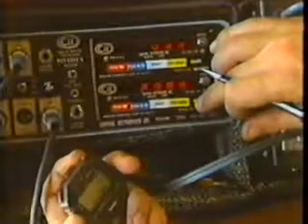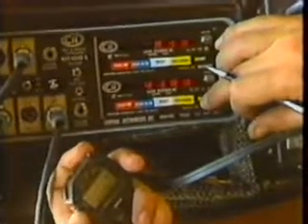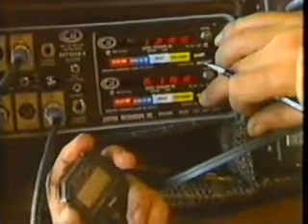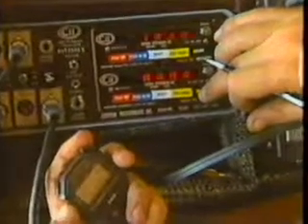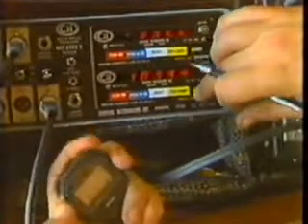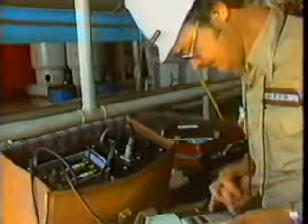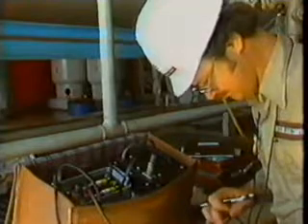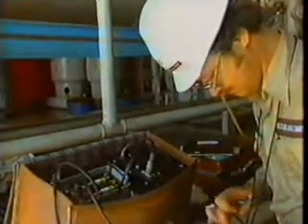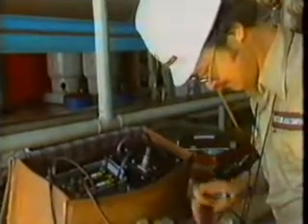Gate the two totalizers together and measure the volume with a minimum of 10,000 pulses. Stop the two totalizers simultaneously, record the readings, and zero the counters for the next measure. Again, to establish repeatability, 5 out of 6 consecutive proves within 0.05% of each other are required.